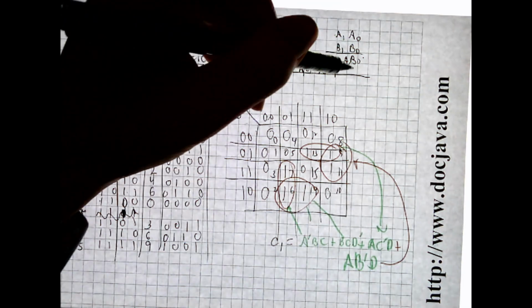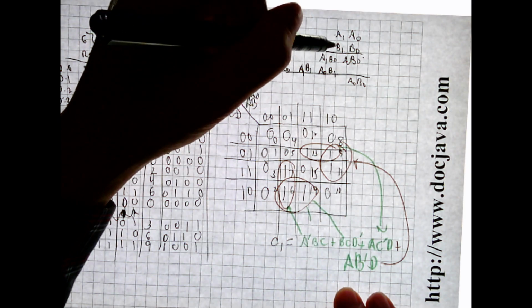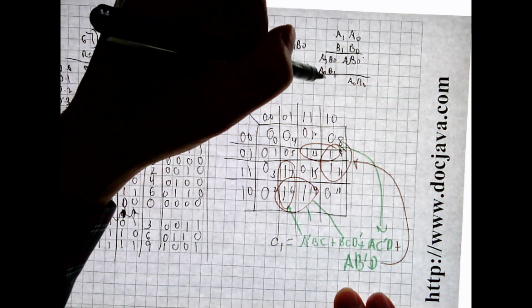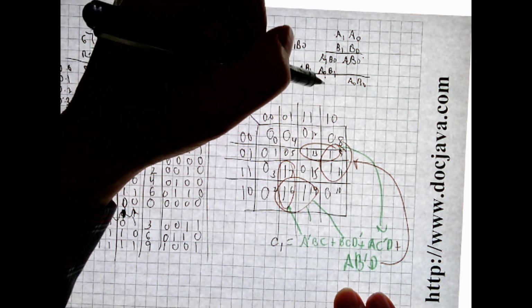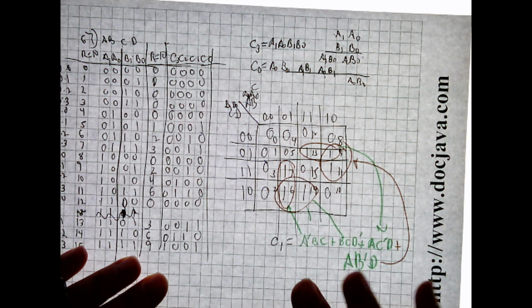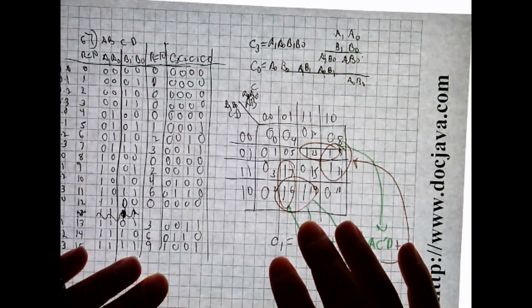then you could just do simple addition. C1 would be A0, B0. And then you'd have these two numbers added, and you'd have to do the carry look ahead. You'd have to take the carry out when you added these two. So you'd do this with an exclusive OR, which is what we're trying to show in the diagram. So there's a couple ways to do it. You could try and write out the multiplication in this way.